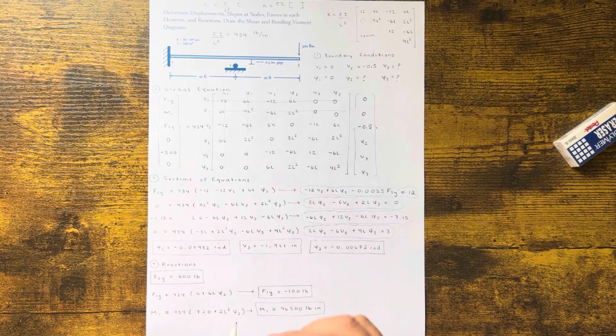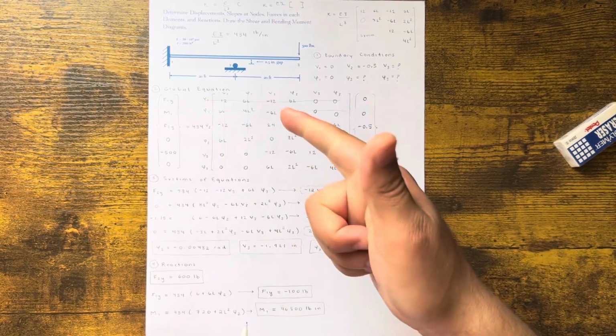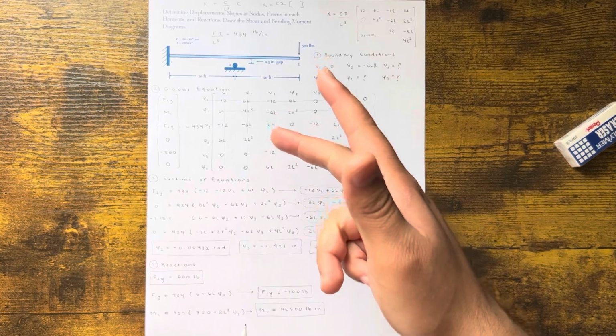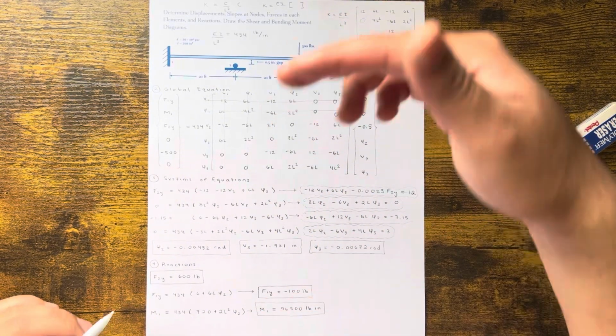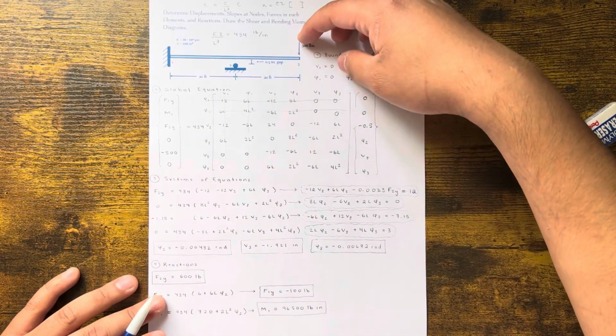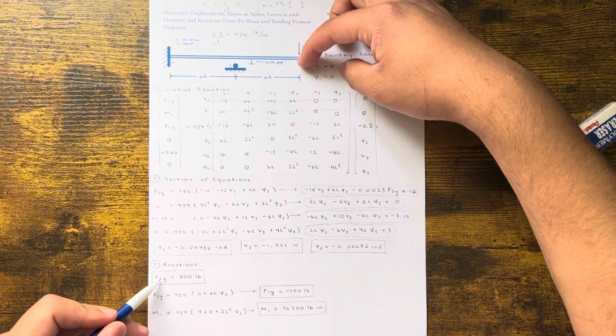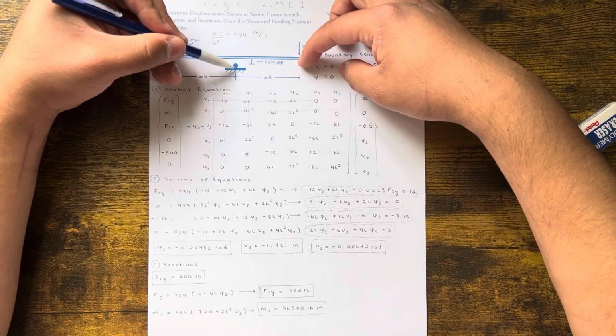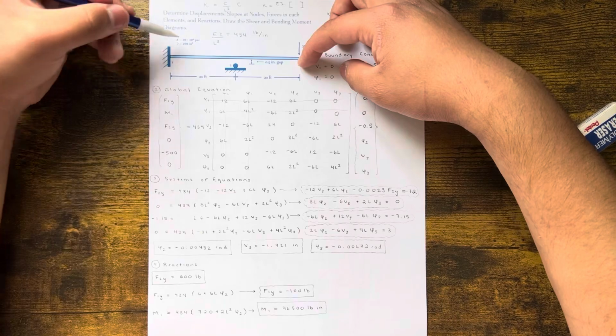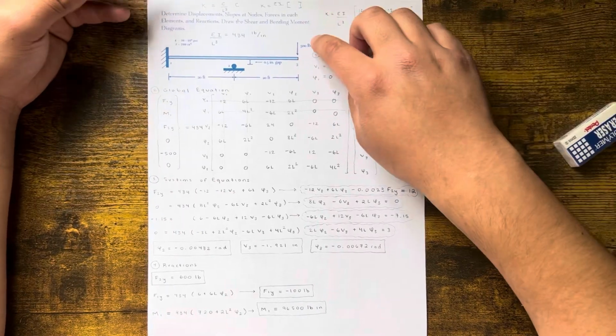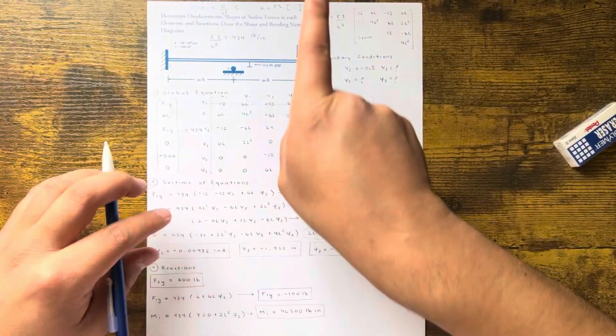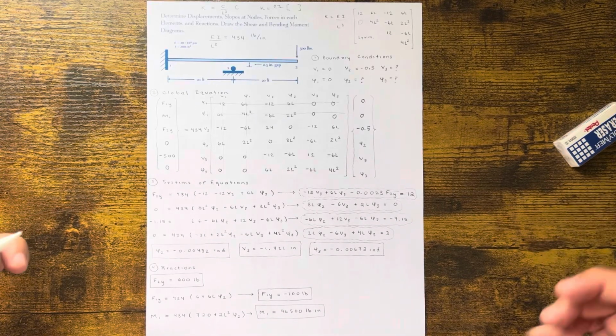Look, you just do the sum of the forces in the X, the sum of the forces in the Y, and then the moments. In this case, there's no X, don't worry about it. Sum of the forces in the Y. You have 500 pounds going down here. F2Y says positive 600, so going up. F1Y says minus 100. Does that make sense? Yeah. 500 and 100 going down, 600 going up. That's an equilibrium. Cool, we're good.